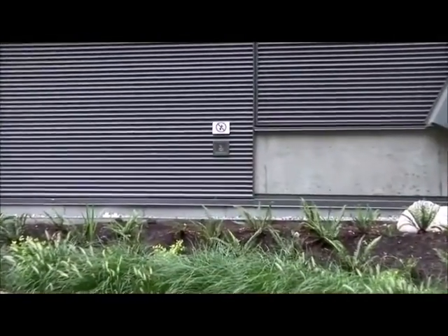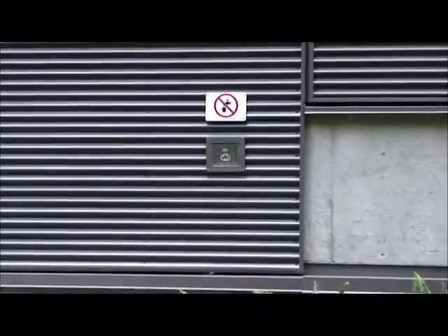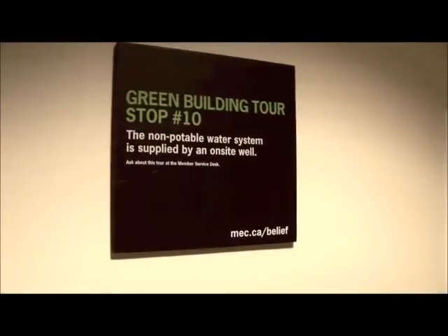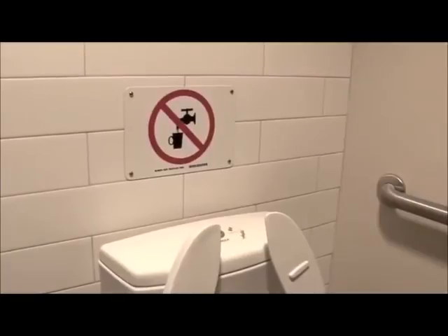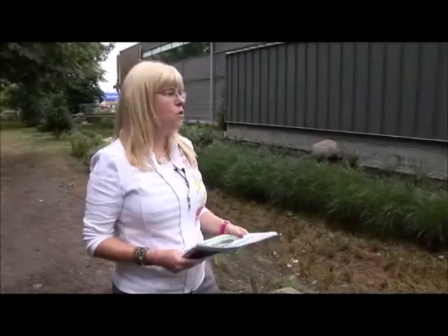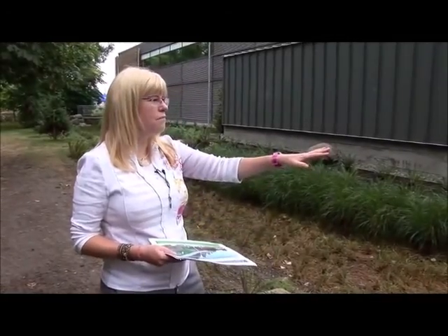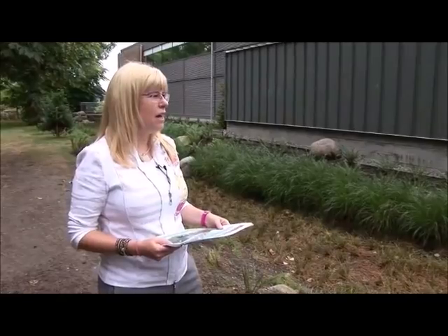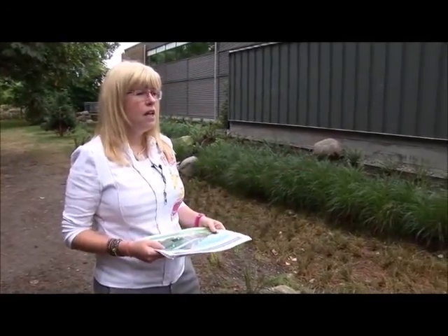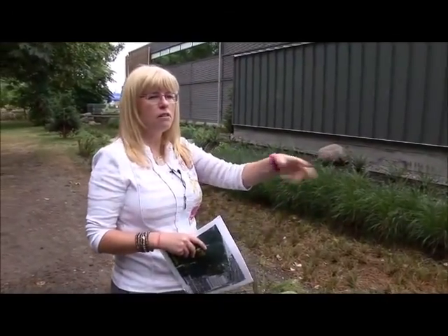We have a groundwater well that takes water from the ground and reuses it in the toilets. Signs in the store's bathrooms inform the public about the source of the toilet water and warn that it's not safe to drink. Most of the contaminants are coming from the parking lot area, and so that can have general stormwater contaminants such as sediment, total suspended solids. It can have oils and grease from vehicle droppings, and it can also have metals. So as they're drained to the rain gardens, they get stormwater treatment through the vegetation and soil layer.